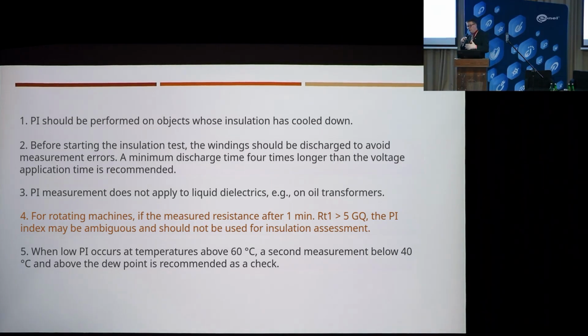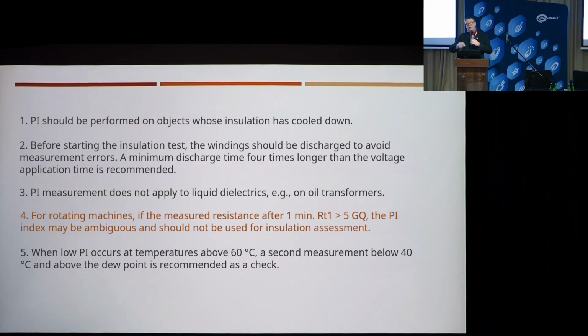Those people only really believed it when there was a completely new motor still in the crate, right? My colleague here, the one I mentioned at the beginning, was there in person and carried out those tests. And in fact, if we rely uncritically on just one factor related to insulation resistance, for example, those coefficients, we can unfortunately make the wrong decisions. Because phenomena like that will not always mean that, in cases where we reach such high insulation resistance values.